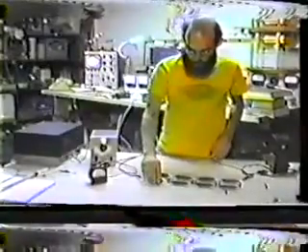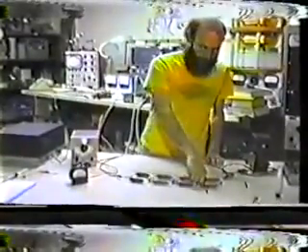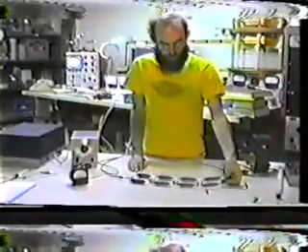And we also can use our fingers too, which serve as very good measuring devices. The voltages are low enough and the frequencies are high enough. We find the coils at the end here getting quite hot, which can be expected. And then they cool right off until at the end, no heat is felt. The capacitors down here are cool. And as we get further down the line, we find the capacitors get warmer. So we find that we have a separation of the heating effect, where the dielectric heating effect, understandably, is occurring where the dielectric energy intensity is maximum, and the magnetic heating effect is maximum at the end where the magnetism is most intense.